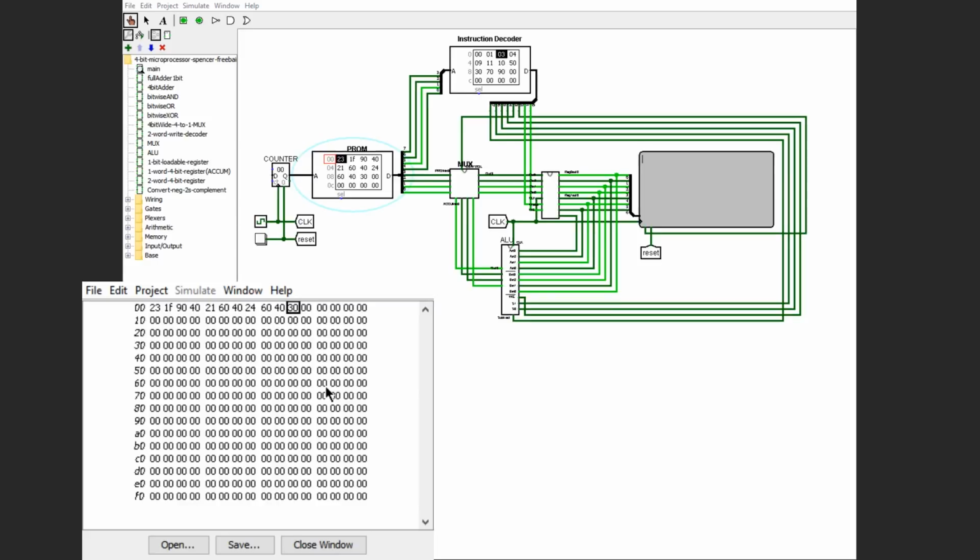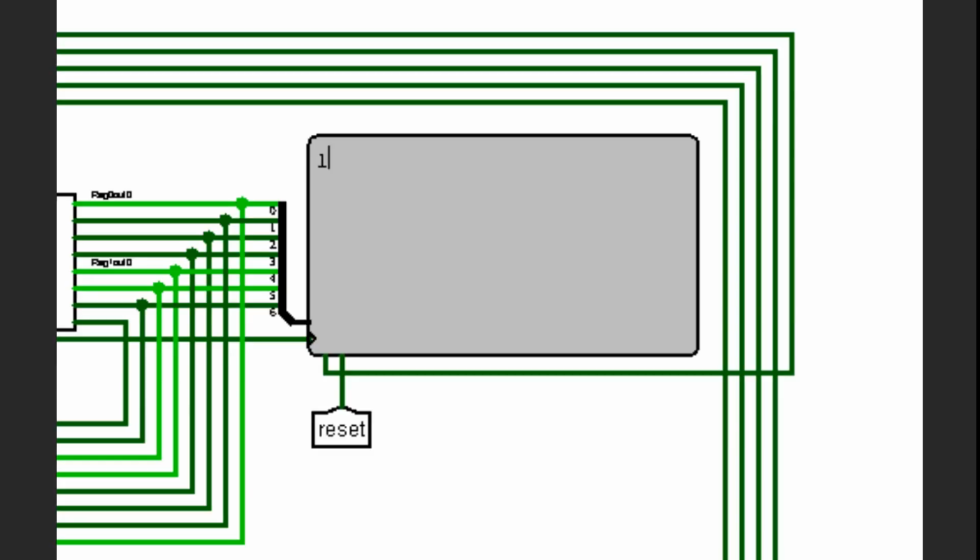Oh, nope, we're going to store the value 3 into register 1, because you need to get the ASCII value, the ASCII number. We need to do 3 and then the number that you want to display. So we already have the number we want to display in register 0. We're putting 3 in register 1, and then we're going to output that, and we will run that, and you get the value of 1. Great, so we've done that.